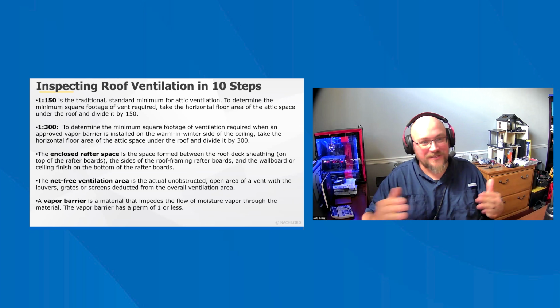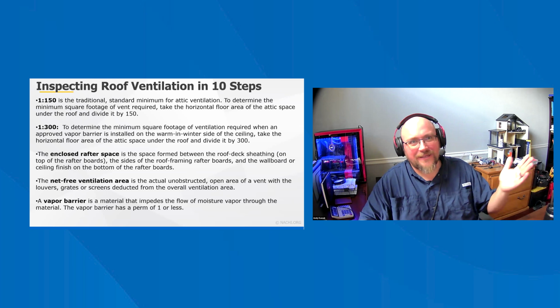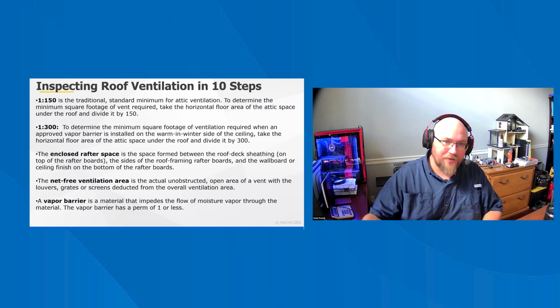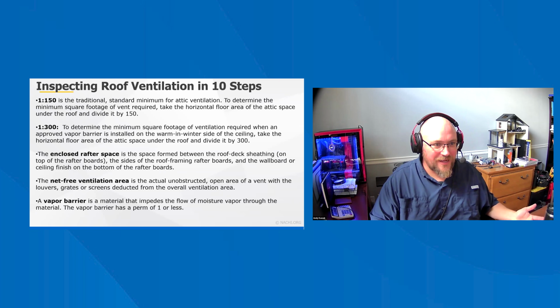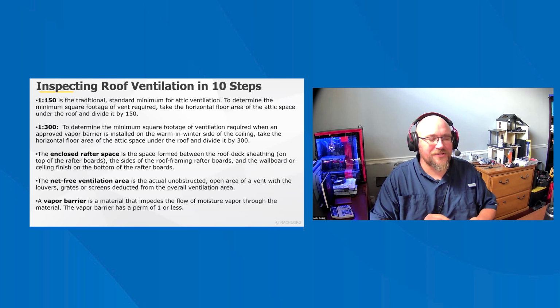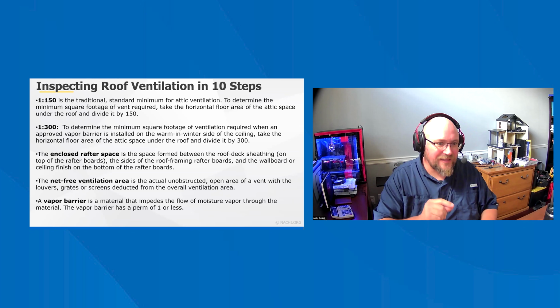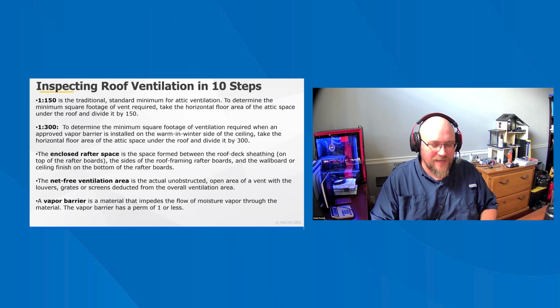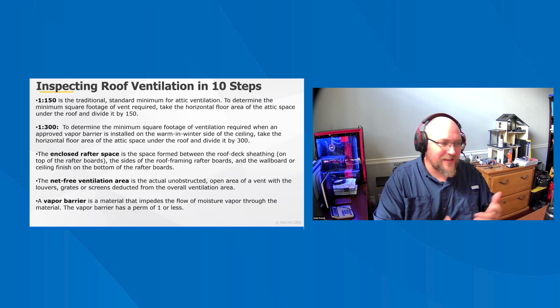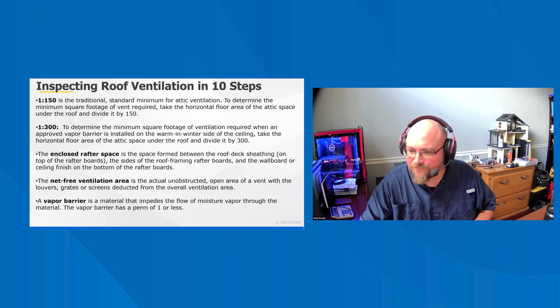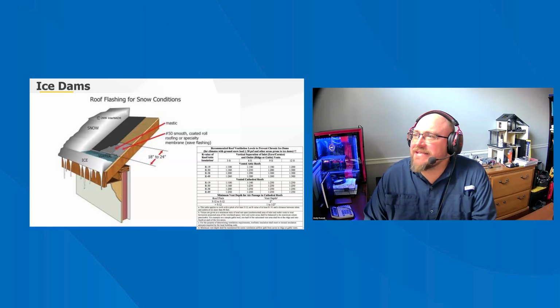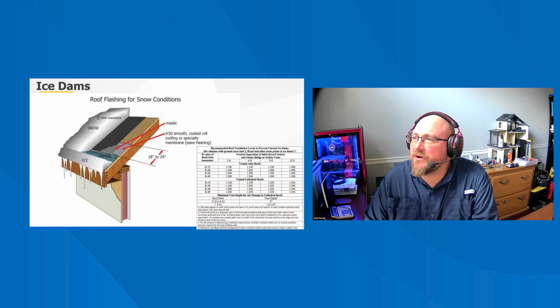But if the roof vents are blocked and you have a 5-year-old roof that looks like a 30-year-old roof, then you know it might be because the ventilation is not correct. So, you're not required to prescribe the repair or completely identify the defect, but it helps you as an inspector to be able to identify defects that will help your client save money, save costs, save energy, all those things. So let's keep going on the ice dams real quick, and then we'll get done with this portion.